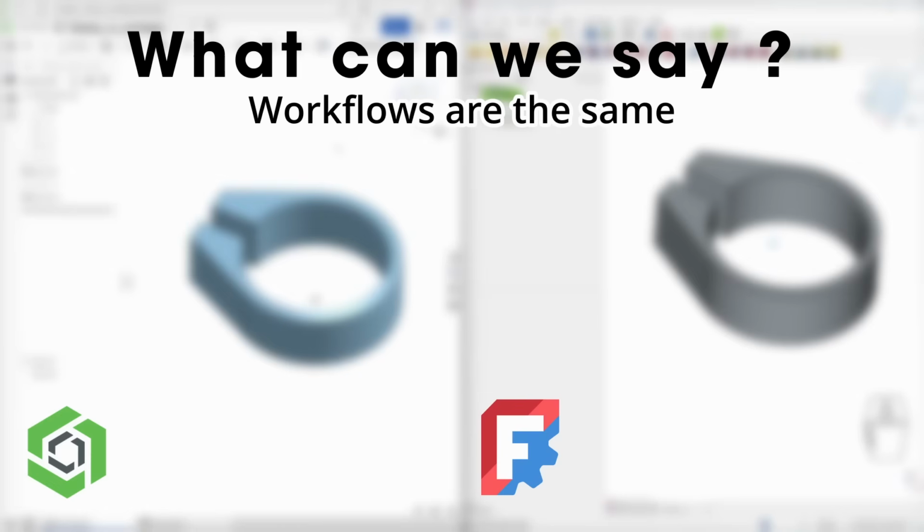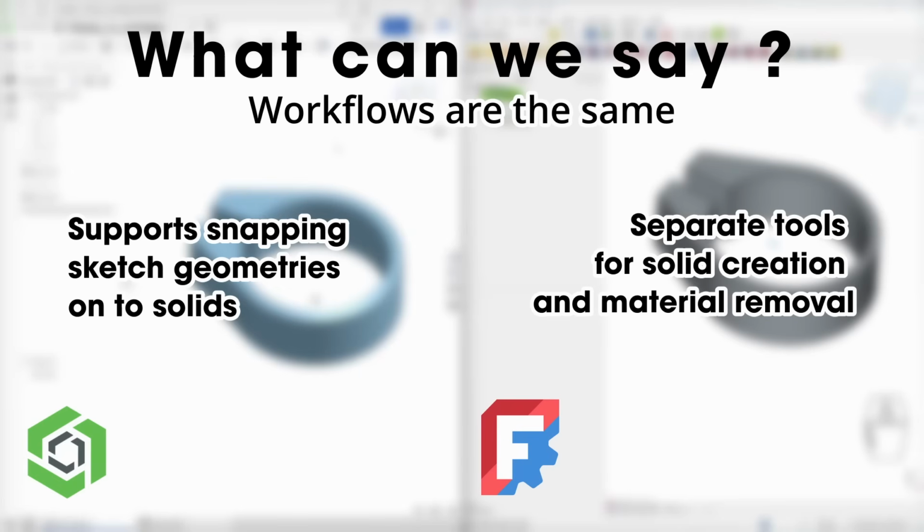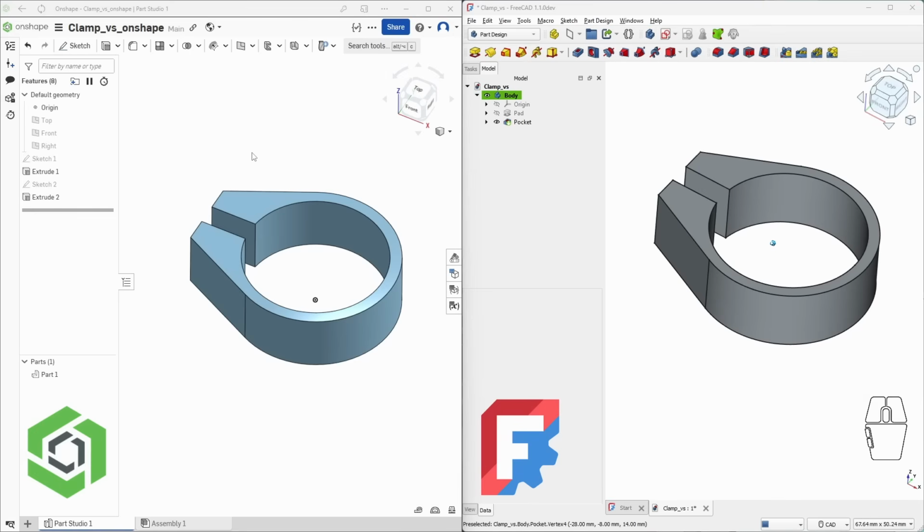However, a big advantage goes to Onshape for its ability to snap geometry directly onto existing solids without needing a projection tool. This is a significant time saver and makes the workflow more intuitive. Another notable difference is that Onshape uses the same tool for both adding and removing material. While this requires one extra click compared to FreeCAD, it simplifies the user interface by reducing the number of tools needed. We will now proceed to the third step, creating a slightly more complex and technical opening to see how the software handles it. Let's start with Onshape.